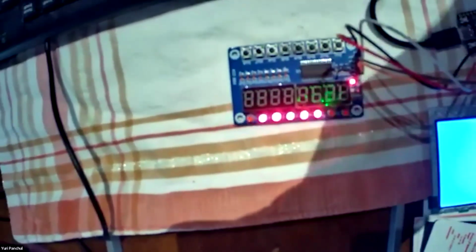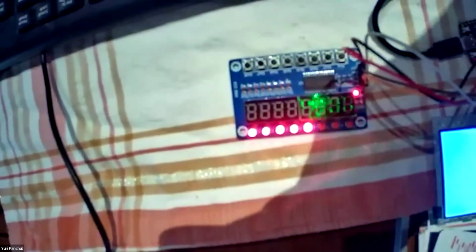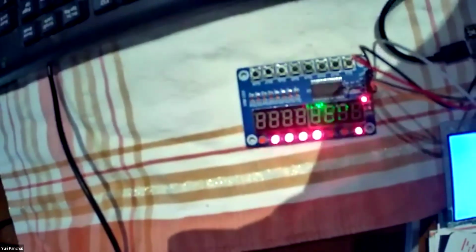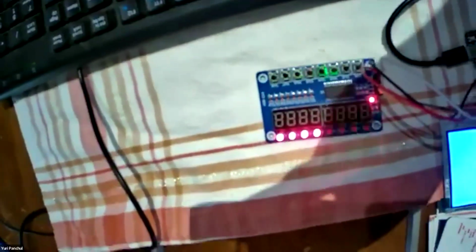So basically, you can look at different bits of this counter, and if you use low bits, it will change faster. If you look at the higher bits, it will change slower. And once we have this, we can use it to create a design of a so-called clock enabler. The reason I am showing it to you is we can use it for displaying something on a graphical screen. So now let's apply our knowledge to a graphical screen.